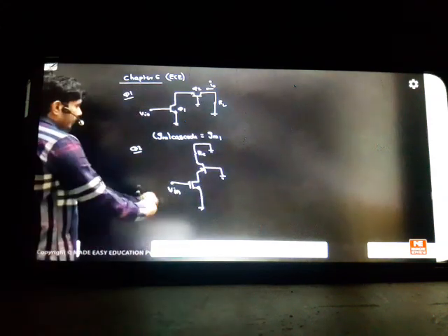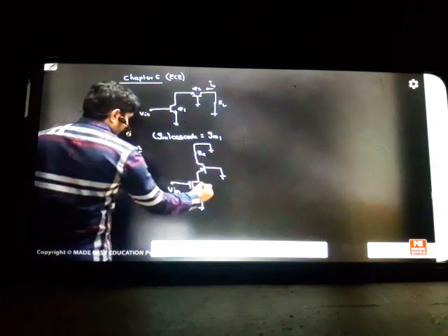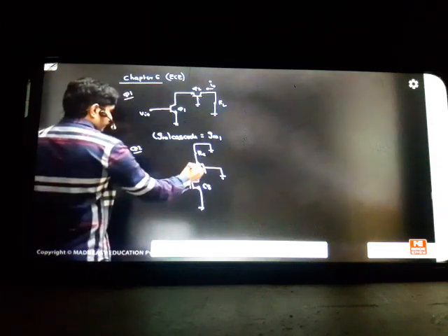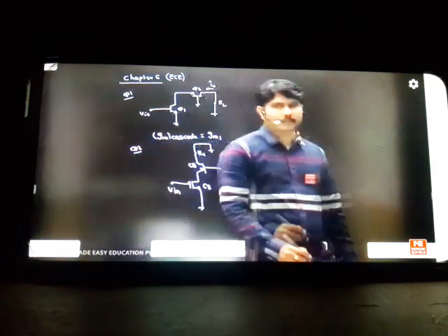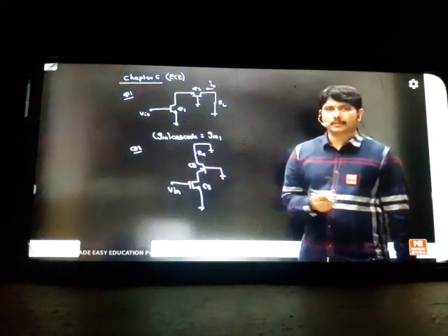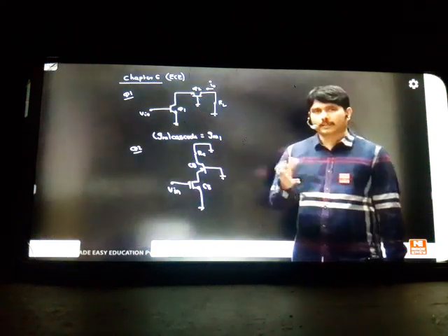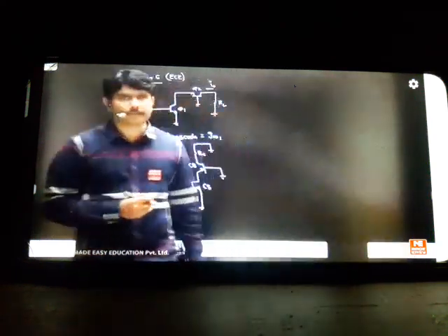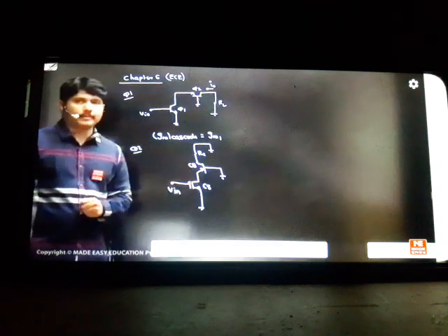If you see clearly, this model looks like a cascode because this is a common source and this is a common base. Please understand that a cascode can be designed with a combination of transistors, which we call composite transistors. You can take a MOSFET, you can take a BJT. The bottom one is a common source, the top is a common base transistor.